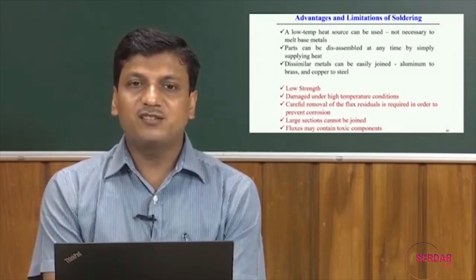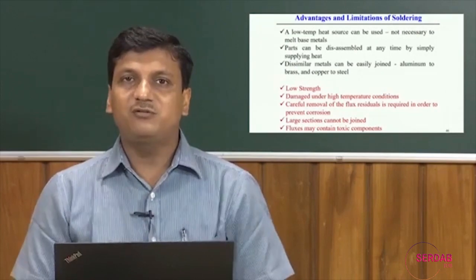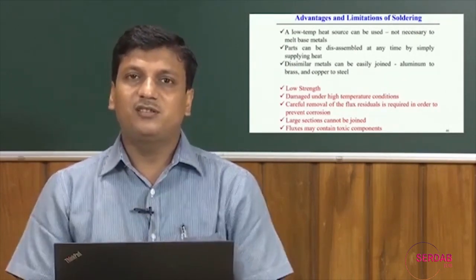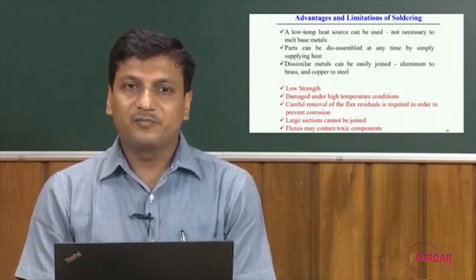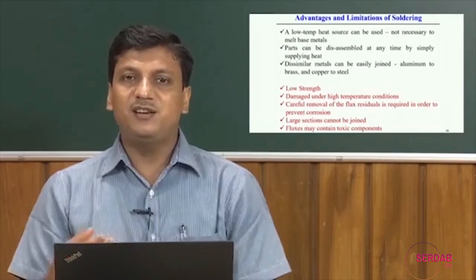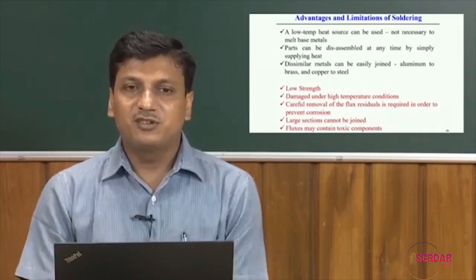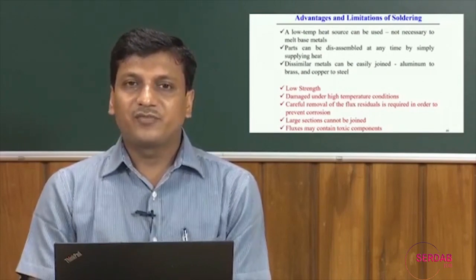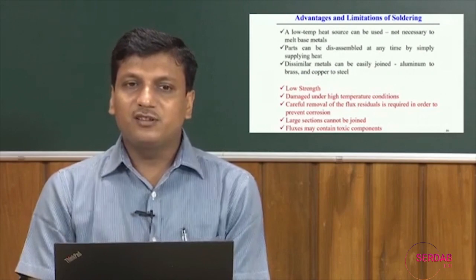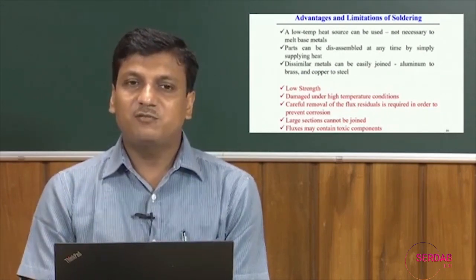Careful removal of the flux residual is sometimes required in order to prevent corrosion of the soldered surface. Large scale sections cannot be joined. Soldering is mainly used for joining very small components, and sometimes for repair purposes.